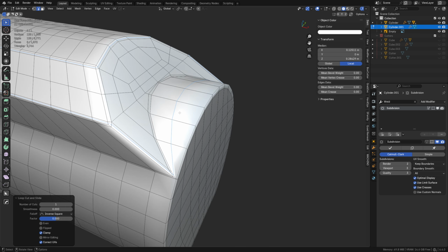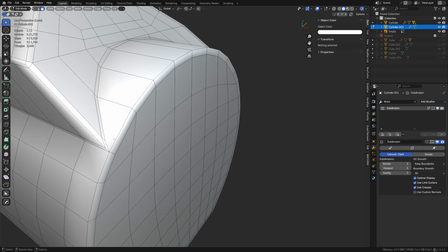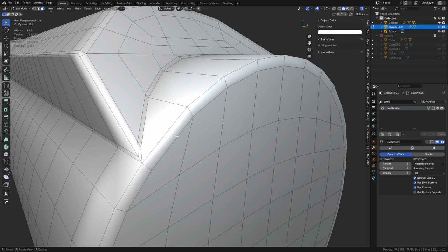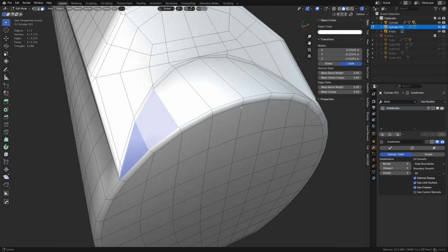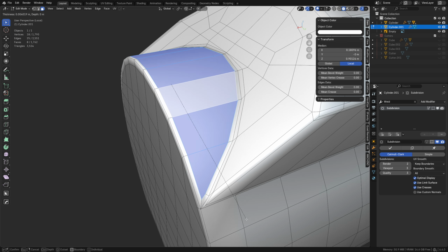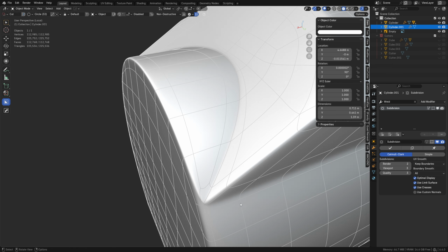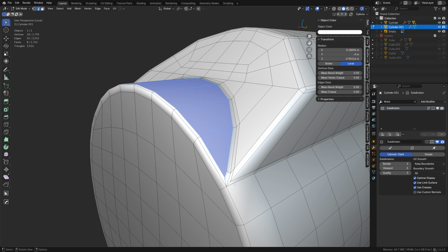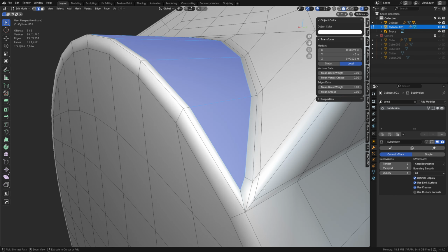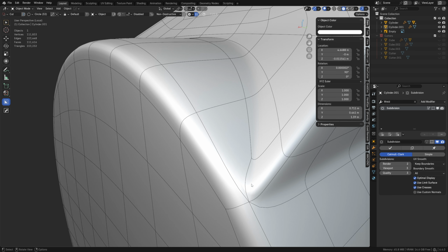But we might really want an additional edge in here. In the way it's going right now, that's maybe not quite what we want, to have that quad like that. Maybe we want more like a triangle. I think for simplicity's sake, I would probably leave it the way it is. But if I needed more topo, and I absolutely did not want to start doing a bunch of weird surgery on that corner, I'd probably just inset it a little bit and then let it rock like that maybe. But you can see that's where things get a little bit iffy as well. So you can leave it alone. Sometimes it's better just to leave it alone, right?